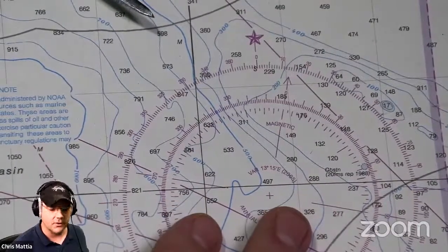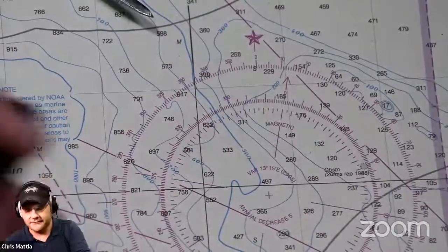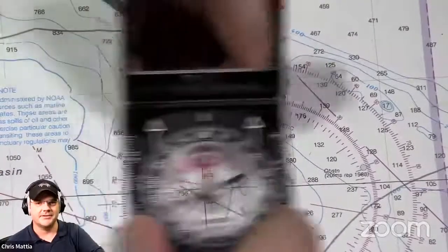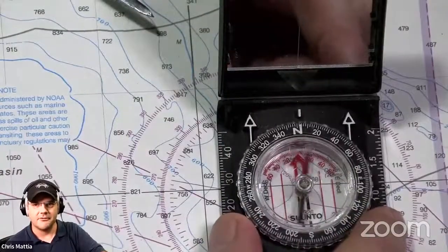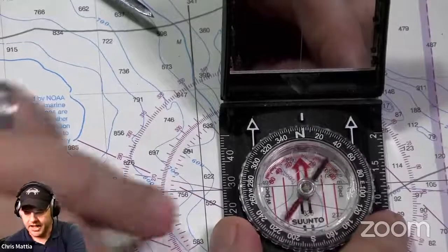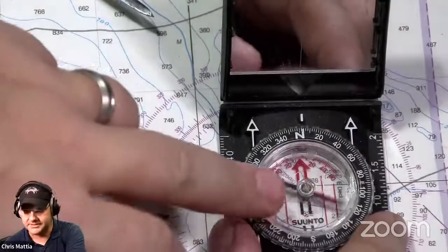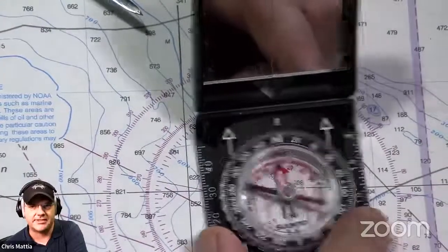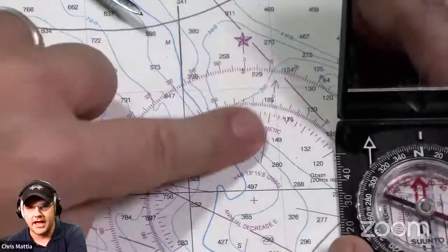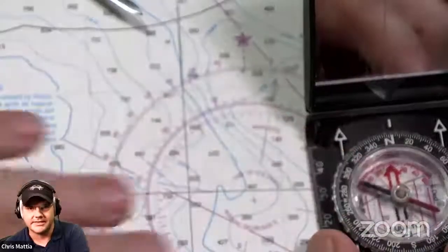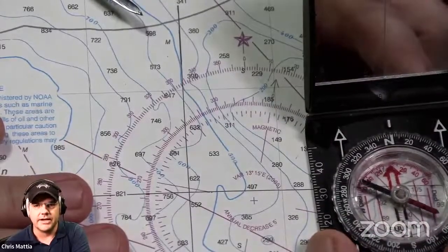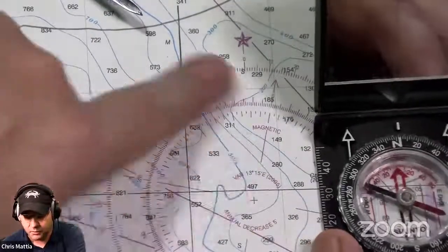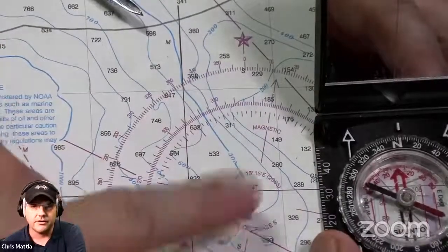Where that makes a difference is if you were to try and get a bearing on your compass, and yeah, I've got a lot of magnets, so I've got to move it to a spot where I'm not getting magnets picking up on here. When your compass finally stops spinning around, you can turn the map physically so that it orients the magnetic line so that it aligns with the north on your compass. Then your map would be properly oriented, so you're able to figure out the locations that you're going. So that's the first thing that you want to look for: what is magnetic north on your map.